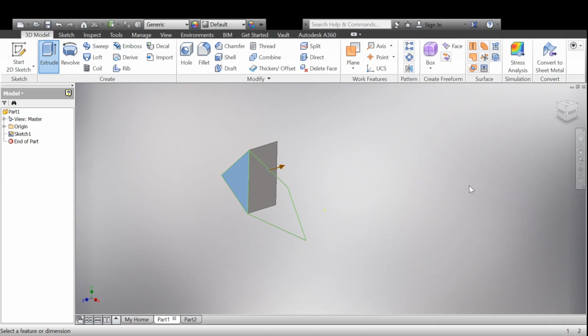The one after that is called a symmetric extrusion, which allows for the extrusion to increase in both directions at the same exact rate. And then the last one is called an asymmetric extrusion, which allows for the front and the back extrusion to be at different distances, which is why we have to specify here 2 different distances.